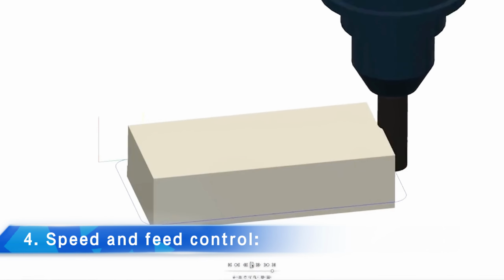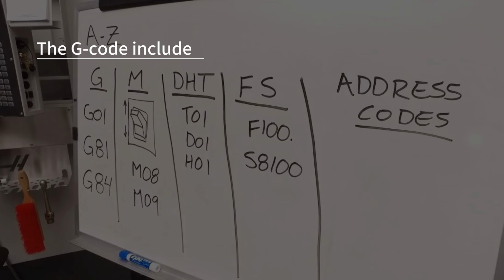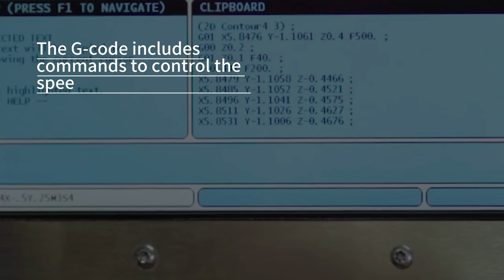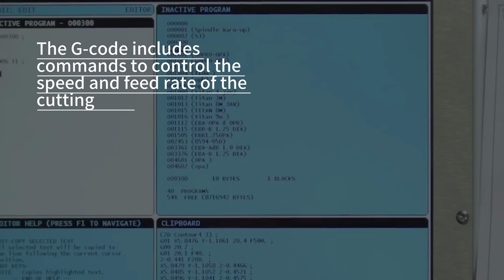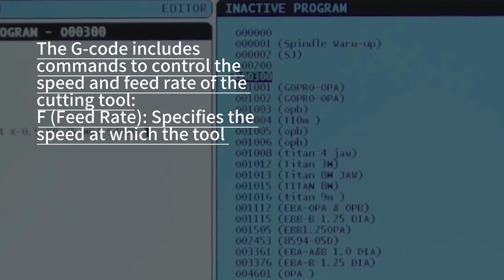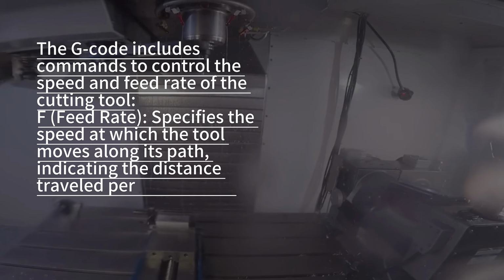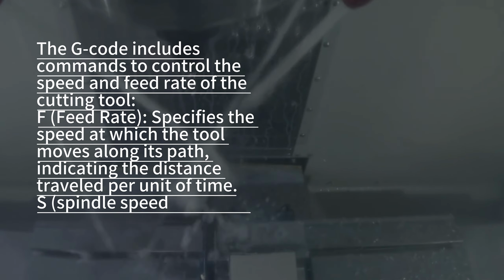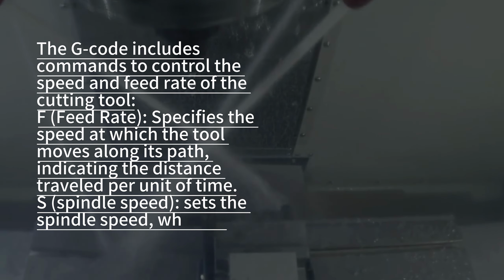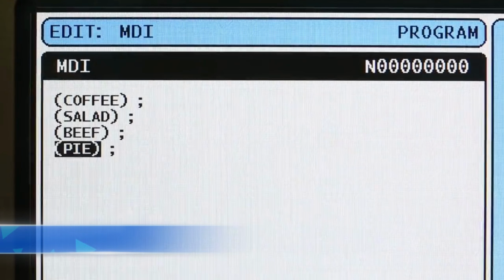4. Speed and feed control. The G-code includes commands to control the speed and feed rate of the cutting tool. F, feed rate, specifies the speed at which the tool moves along its path, indicating the distance traveled per unit of time. S, spindle speed, sets the spindle speed, which is critical for cutting operations.